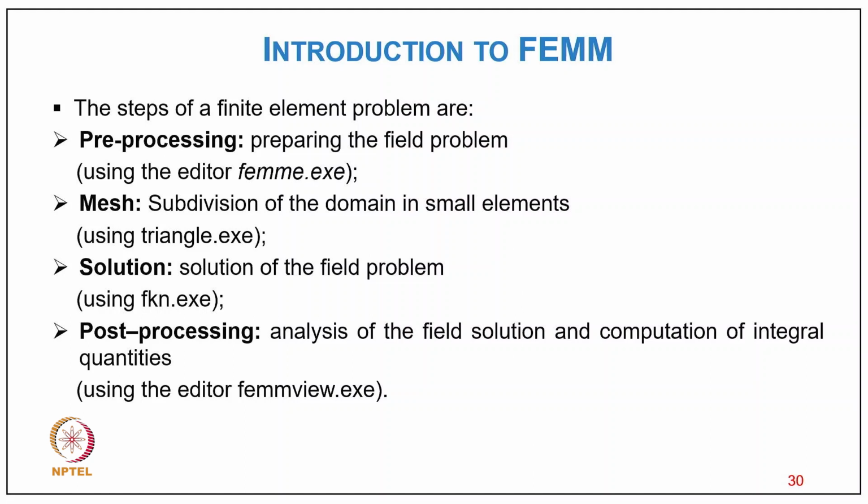Now coming to the steps of finite element problems. Preprocessing: preparing the field problem using the editor femm.exe. Mesh: subdivision of the domain into small elements using triangle.exe. Solution of the field problem using fkn.exe, and post processing: analysis of the field solution and computation of integral quantities using the editor femmview.exe.